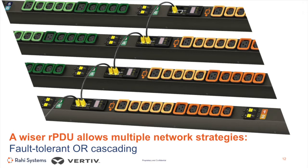So if this was a long daisy chain, I would still have visibility to the PDUs downstream. The network would self-heal in a way using a spanning tree protocol to capture the data from those downstream PDUs. So they remain, of course, online and monitored. In this daisy chain fashion, it also minimizes the number of network ports that a rPDU or rPDUs would consume on a presumably expensive network switch.